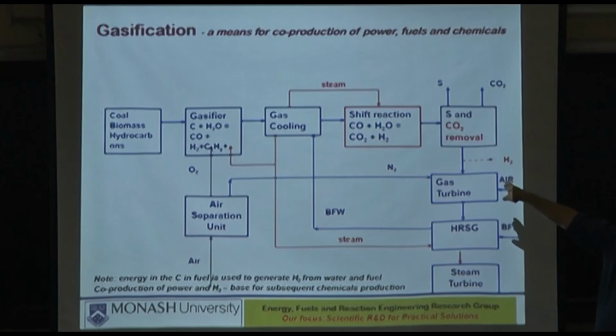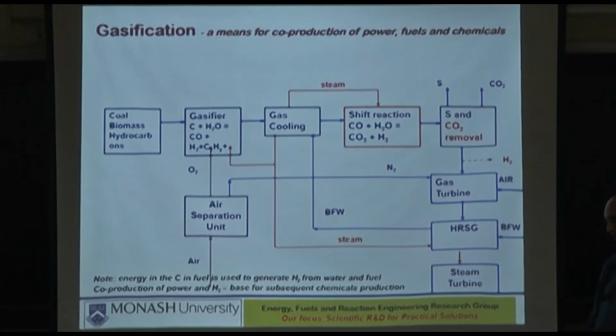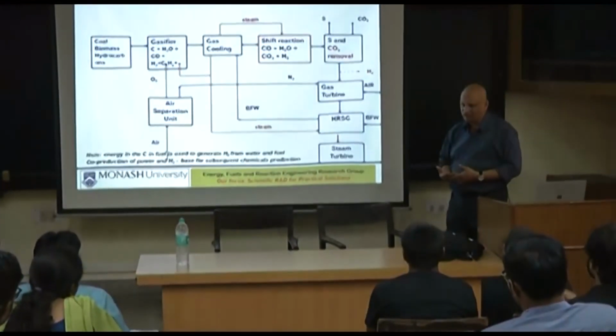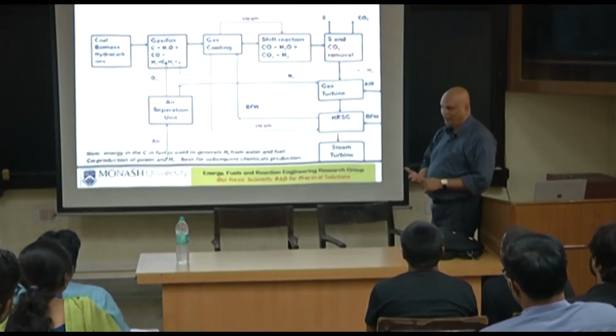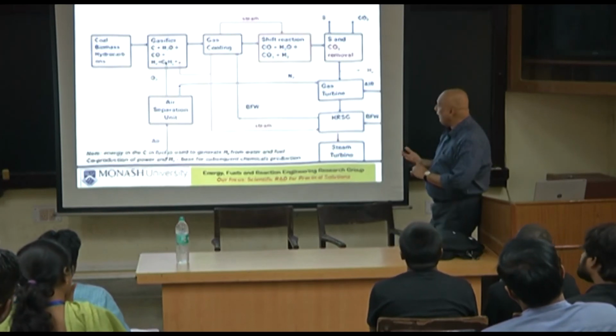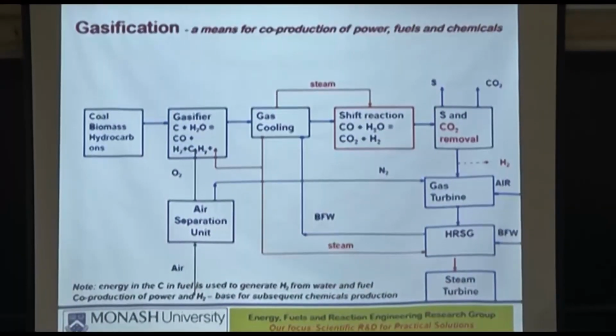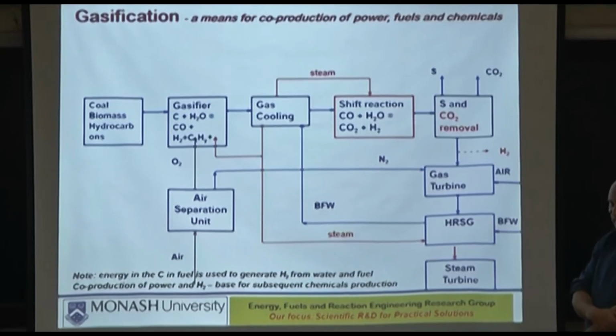Here, outside. But if you want to do it inside, yeah, that's what is usually the case. No, not sprinkled water. Usually you do it separately. Because if you spray water inside, the gas will become saturated in water vapor. So the gas will now have hydrogen, CO2, and the sprayed water vapor, which you don't want. So it's better to do it indirectly.